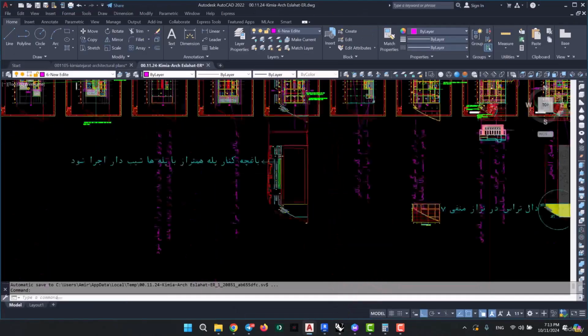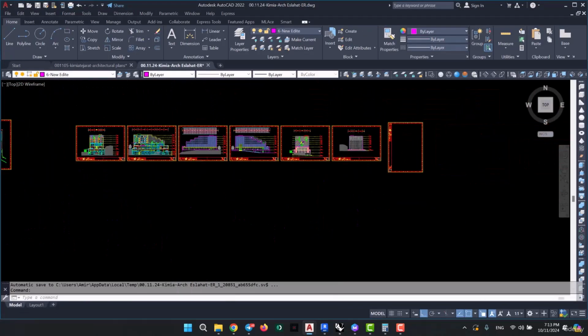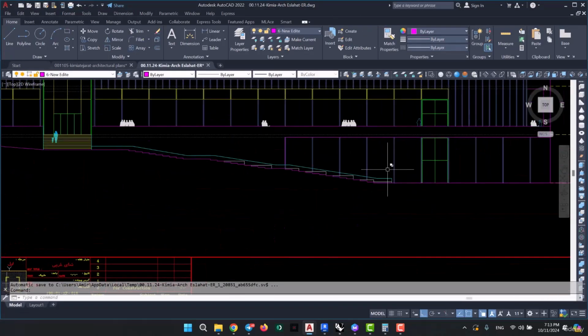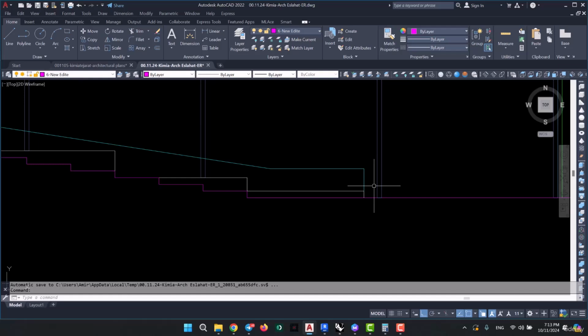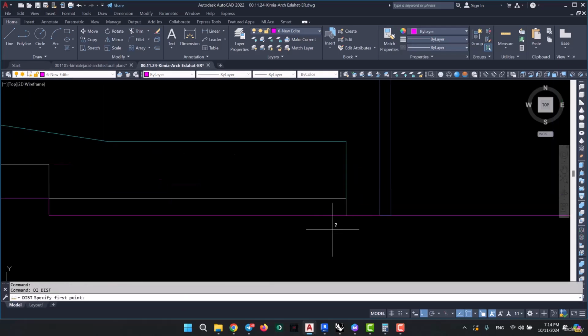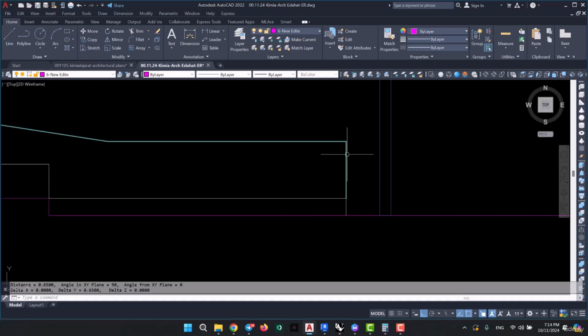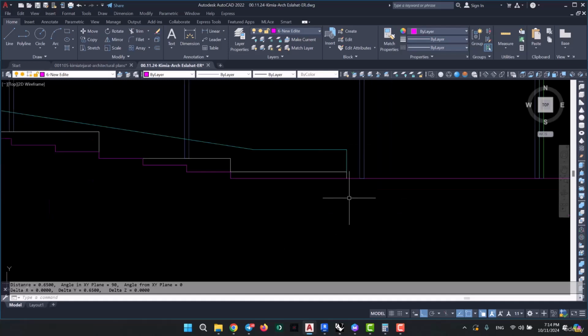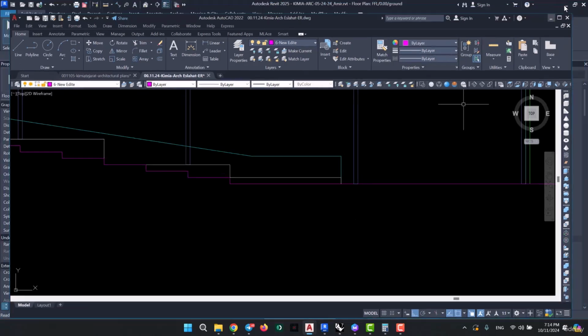Now let's go over here. This right here is the stair sidewall, which you can see is designed aligned with the slope of the stairs. And you could also use this AutoCAD file to measure its distance and check its dimensions. So from here to here, that'll be, for example, 65 centimeters. And so now we know that the elevation of this stair sidewall is of that value.